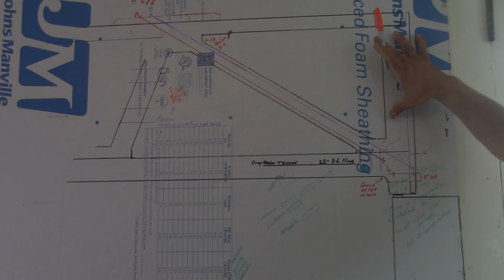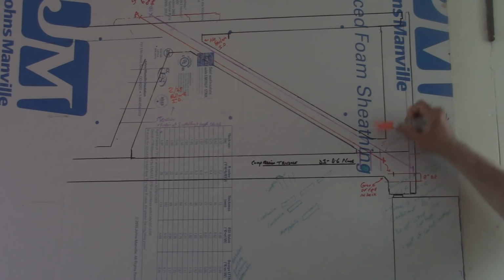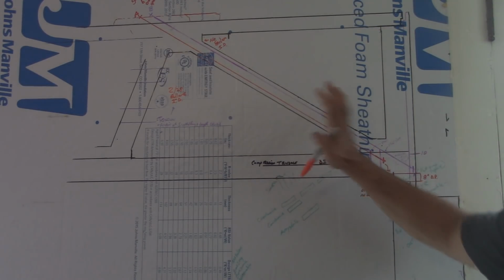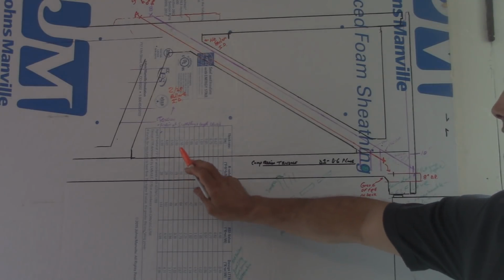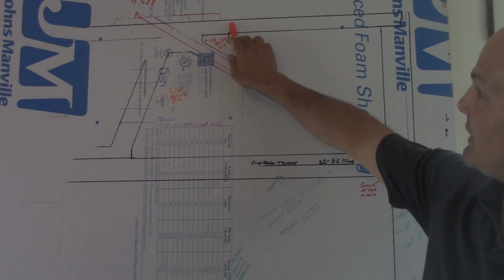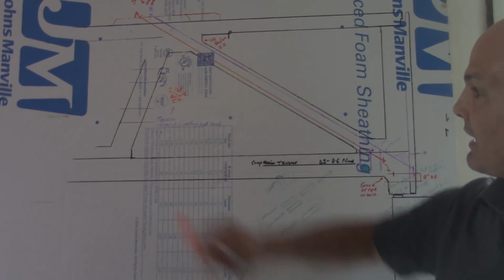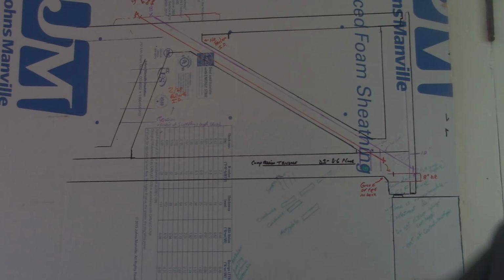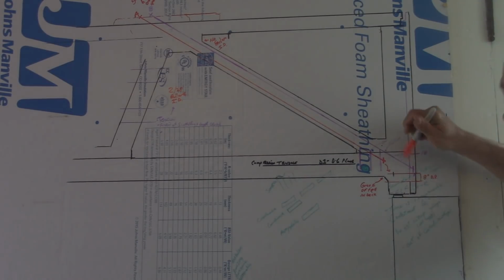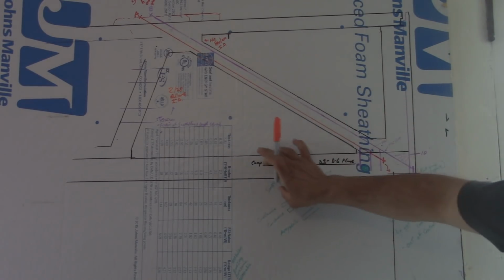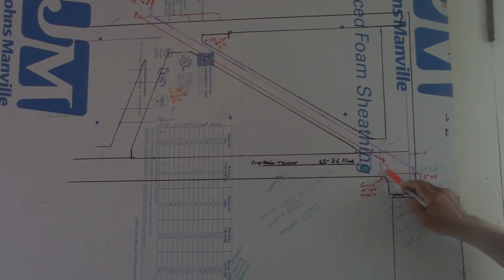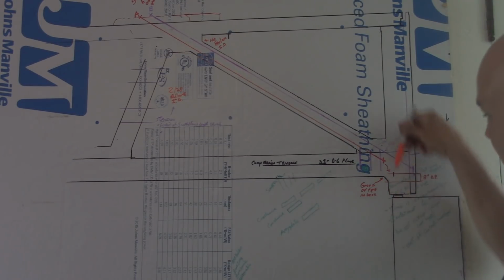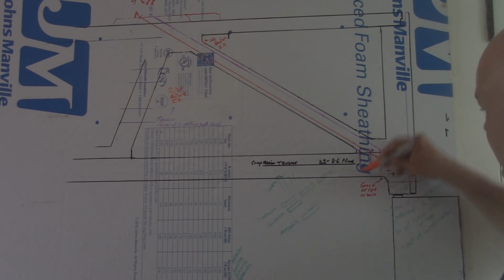But why would it just bend over? Well, because it was anchored at the base when this started failing. The failure is out here. This is where it fails, here and here approximately. How do we get the forces out there to make it fail here? Well, let's talk about shear first. So, in a typical deck, the shear point weakness would be here where the two planes meet.